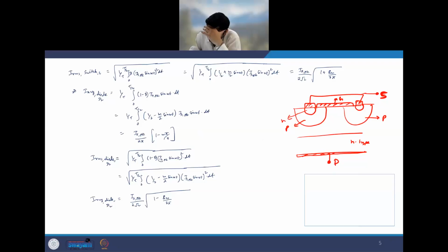So what happens is that whenever you apply the positive potential, you will have a lot of electrons which come over here, and that is when this PN junction breaks down, and then you will form the channel. Now once the channel is formed, your current can go in this direction as well as in this direction. Both directions it can flow. And in the reverse direction, if the voltage across source to drain is smaller than the body diode, because this P and N junction will correspond to the body diode.